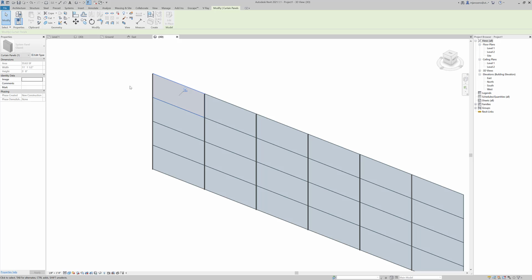60 square foot max, but you can see because of the max spacing, just like our maximum spacing for the beams, it adjusts to something slightly smaller because the chance of me drawing this wall in randomly at a dimension that would perfectly get this to be 60 square feet is pretty low. So it's 55 square feet. So you could always check to see if you're in sort of an economical realm here.